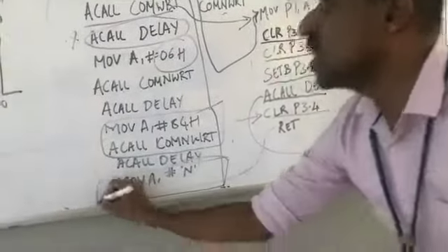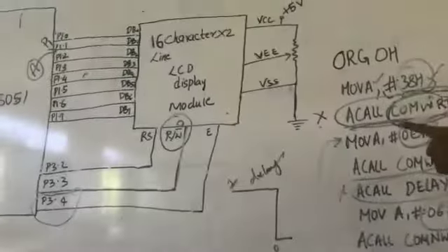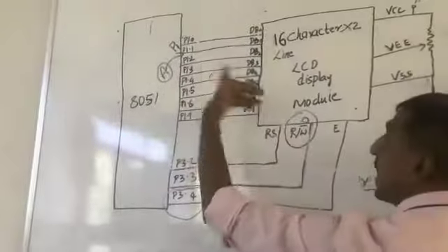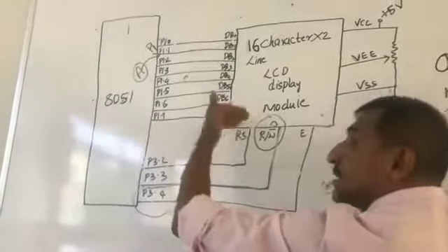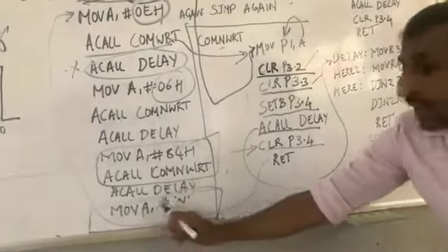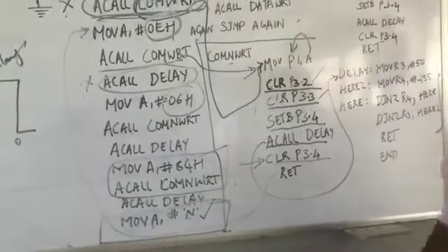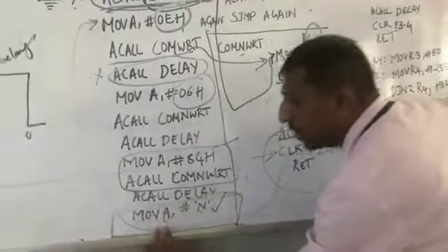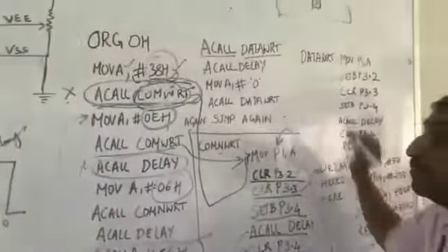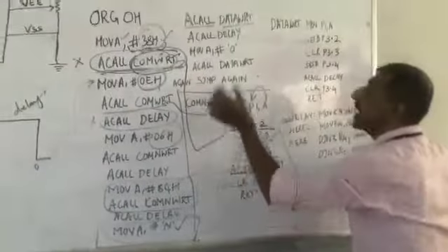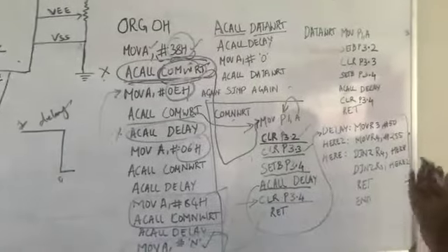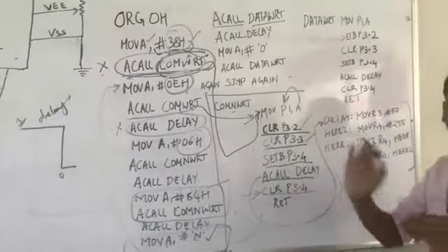that now, since all the commands are executed and the LCD is now ready to display the data, from 8051 we start sending the data that we would want to display. So here I am sending N into the accumulator. What happens here? Actually, the ASCII character of N gets stored into the accumulator. After that, this time I will call one more subroutine, but not the command write, but the data write. Means this time I would want to execute RS equals data register, not command register.